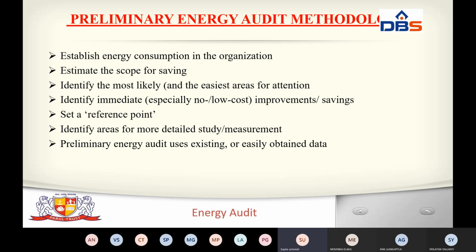What is the inspection of this audit based on? This inspection is based on visual verification, study of installed equipment and operating data, and detailed analysis of recorded energy consumption collected during the benchmark phase. First the visual verifications are inspected, then the installed equipment and operating data are studied, along with the recorded energy consumption collected during the first audit, the benchmark audit. This is the main inspection of the walk-through audit.